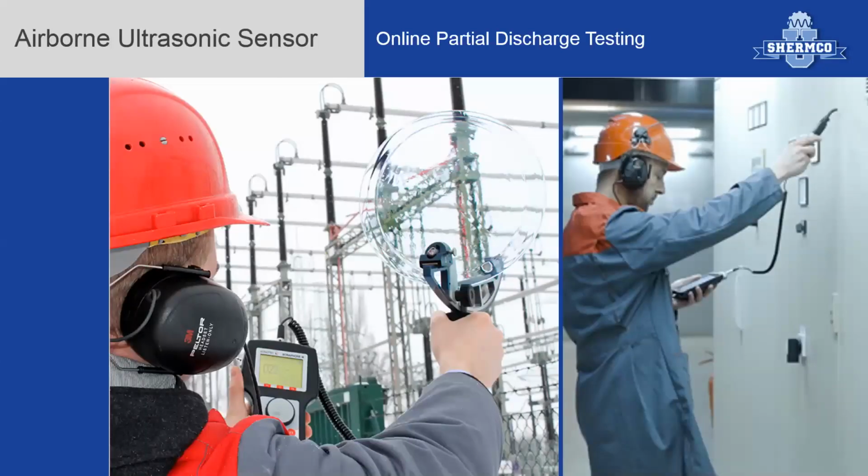All right, let's move into airborne ultrasonic sensors. Airborne ultrasonic sensors include things called parabolic dishes and ultrasonic extension wands, and these devices typically operate in a frequency band of about 20 kilohertz out to about 80 kilohertz, and will normally offer a center frequency somewhere in the area of about 40 kilohertz. Again, that may vary from manufacturer to manufacturer.